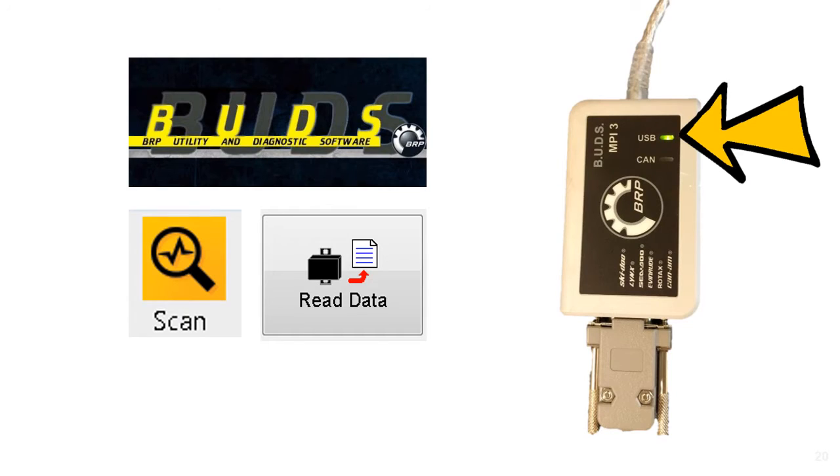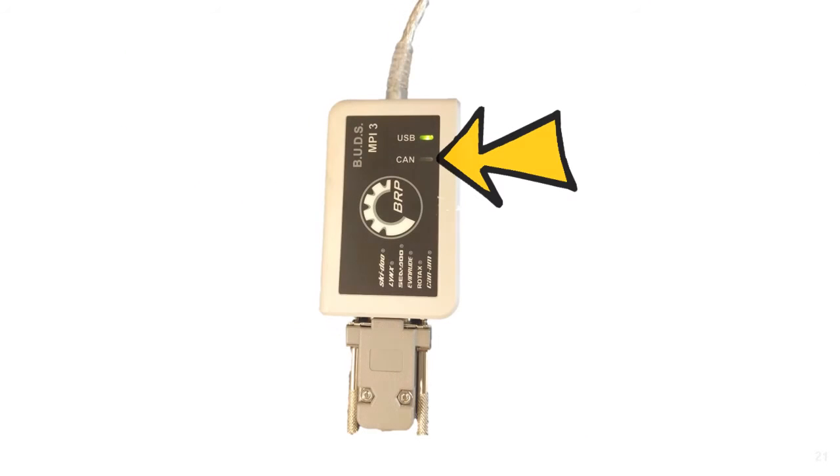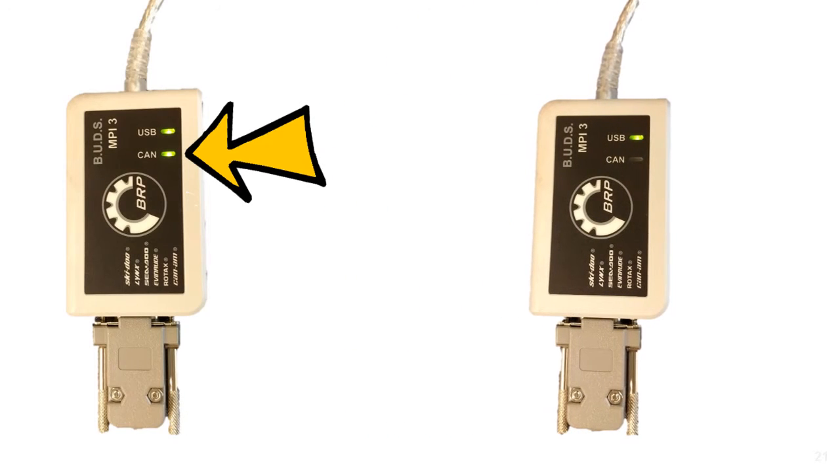If you suspect a CAN communication problem, the first test is to connect BUDS and try to read the vehicle. Make sure the USB telltale light is on. If not, check your BUDS installation, connections, and drivers. If the CAN telltale light is off on the MPI, the vehicle is not responding on the CAN network. Look for a problem affecting the entire network. If the CAN telltale light is on, some modules are communicating on the CAN network. Look for a problem affecting individual modules.